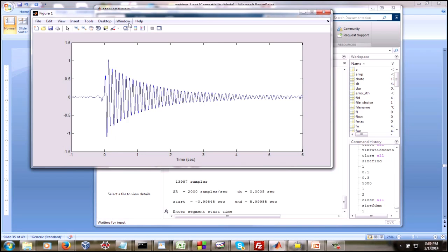And each time we get a candidate waveform, we're going to subtract it from the raw data, and the idea is to minimize the residual error. So we want to come up with the best curve fit, and once we've done that, we've indirectly found what the natural frequency and damping are for this drop transient.